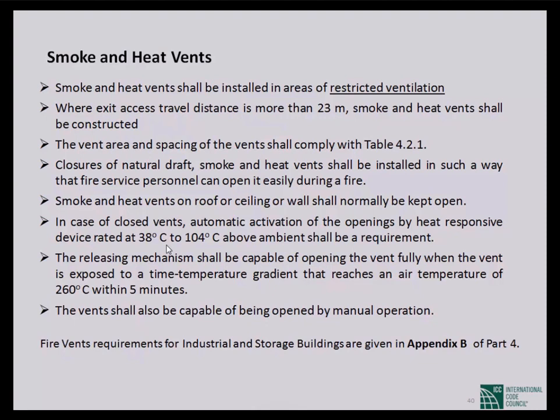In case of closed vents, automatic activation of the opening by a heat-sensitive device above the ambient temperature shall be required. So the vent will remain closed, but at a certain temperature it has to open. So how does it open? There are two types of mechanism. At a certain temperature it will melt down and open, or at a certain temperature it will be automatically activated by an electrical switch or spring switch so that it will open. So this is the releasing mechanism. Some releasing mechanism you have to put in a vent.